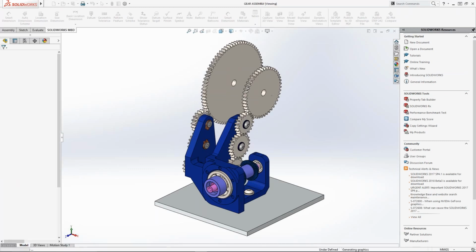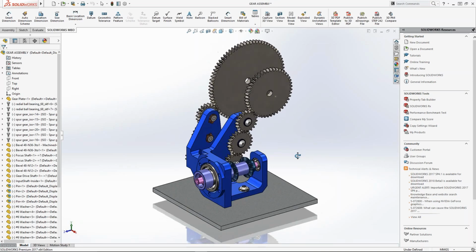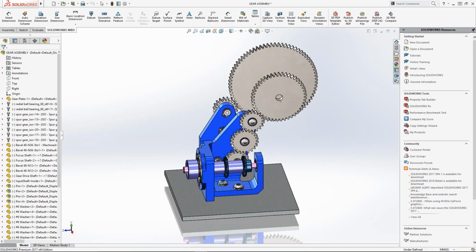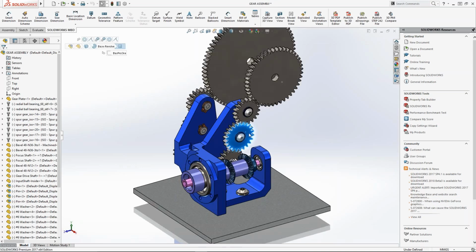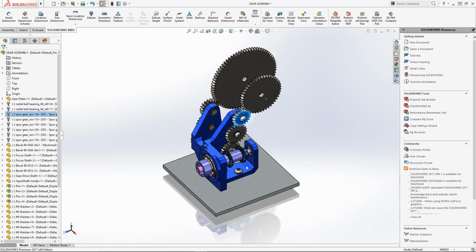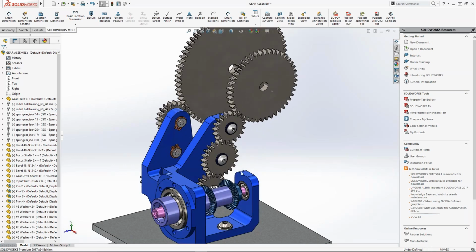In an assembly like this, which is actually an underwater camera housing, we really have precise fits through all of these parts. We need really tight tolerances, for example, where all of these gears mesh together. Right? It's really critical that we have accurate dimensions for this assembly to function as intended. So obviously this can mean really high cost, but if we carefully consider geometric dimensioning and tolerancing, we can actually lower costs in some cases if it's done properly.